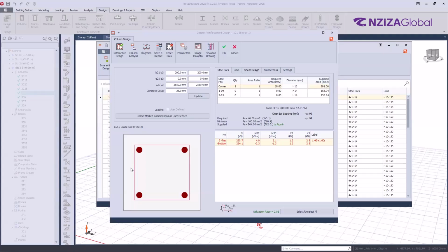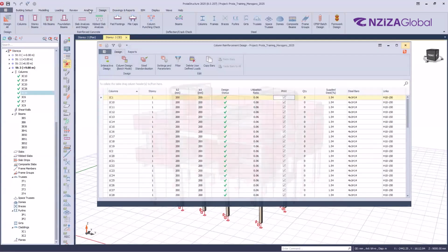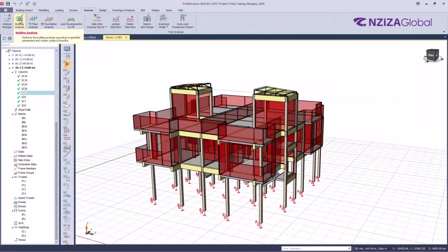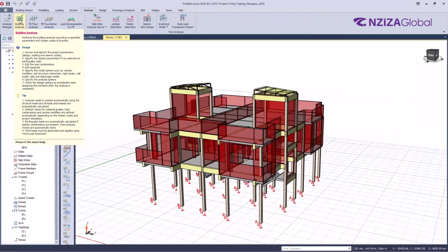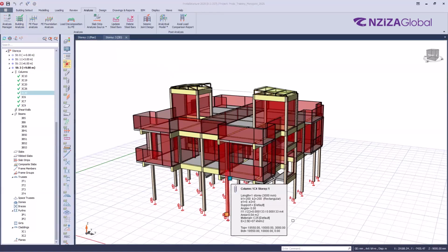So if you are having that pop-up of grading analysis, it means that your grading analysis is not active. Make sure that it is ticked. So to make sure that everything goes okay, repeat the grading analysis. I have mentioned that after doing the analysis, whenever you make any change, your analysis will expire. So you have to redo the analysis. Okay, so try that.